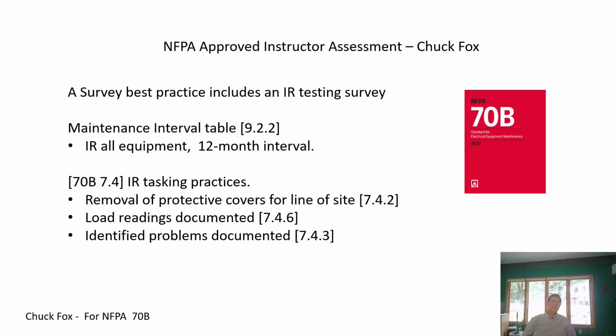A best practice, of course, when we talk about that initial survey is to ultimately include in that survey what components are tasking. Of course, a best practice begins with using infrared thermography as a testing survey, and that's actually documented as an element within the maintenance interval table under Chapter 9.2.2. It basically says that all equipment shall be tested with infrared thermography for an interval not to exceed 12 months.